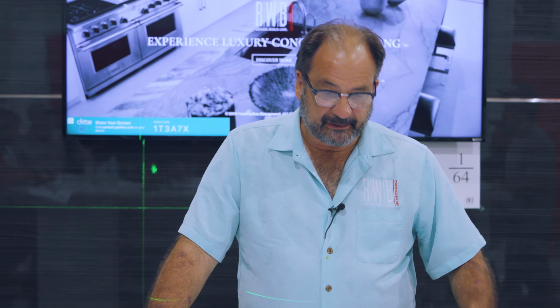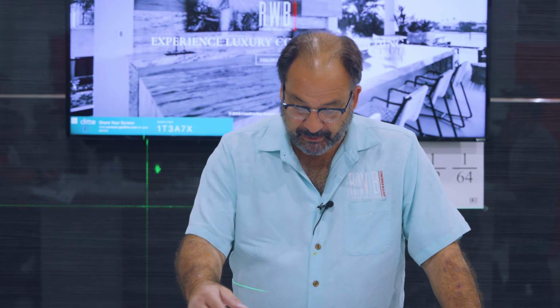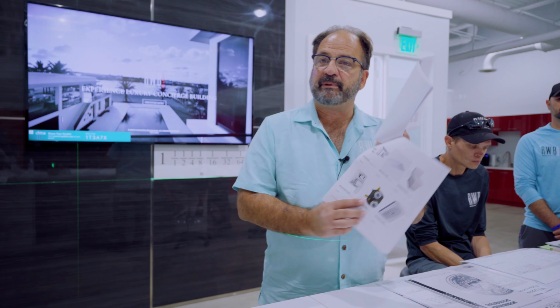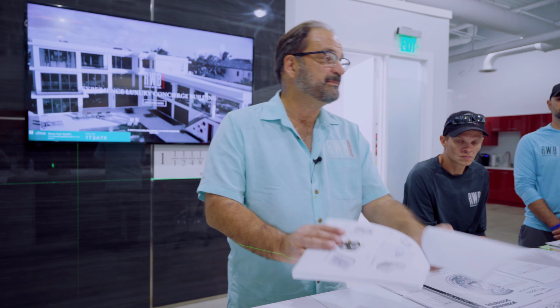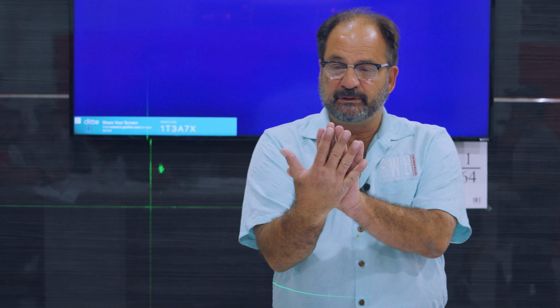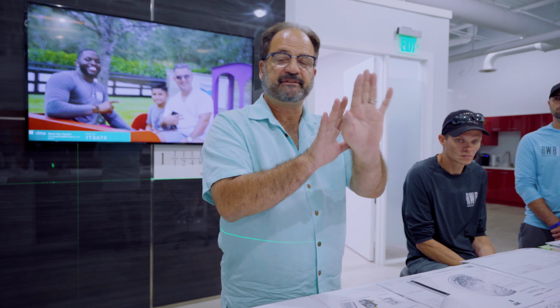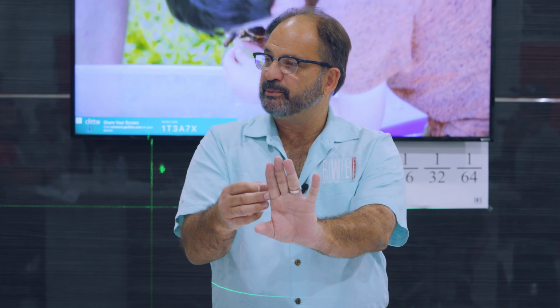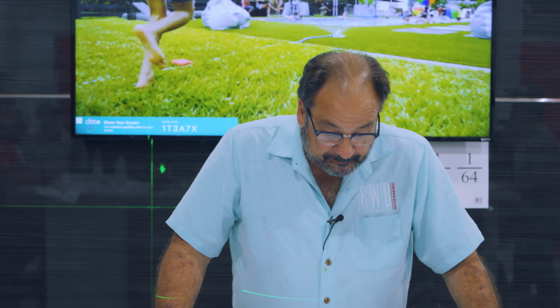This doesn't necessarily mean everything drawn is going to work perfectly. Sometimes you get a shower body, and the shower bodies will be listed here. And in some cases, the walls aren't thick enough to hold the shower body. Or there's a relationship of where the shower body has to be in relationship to the face so that the cap fits on right. So you have to look and say, here's the front of the wall, I have cement board, then I have stone, so my distance off of this wall is going to be X. That will let you locate it within the wall.